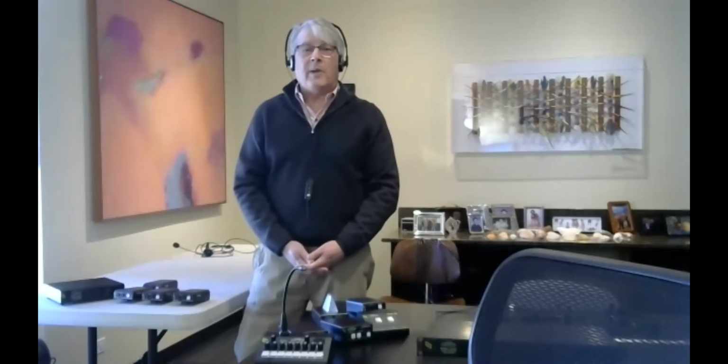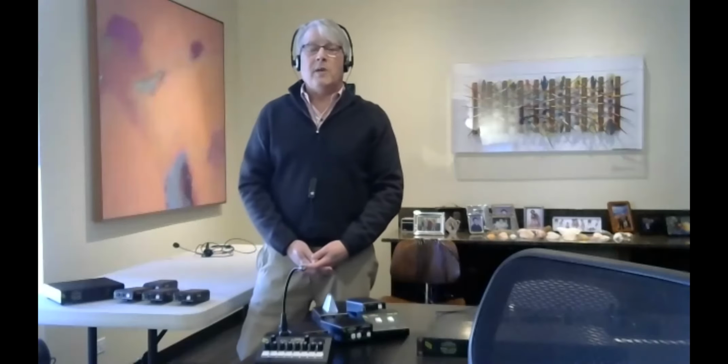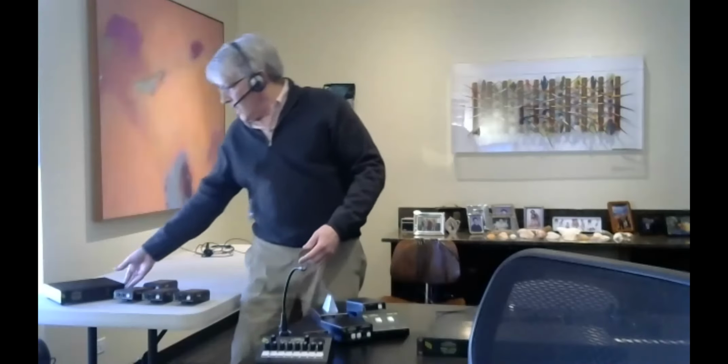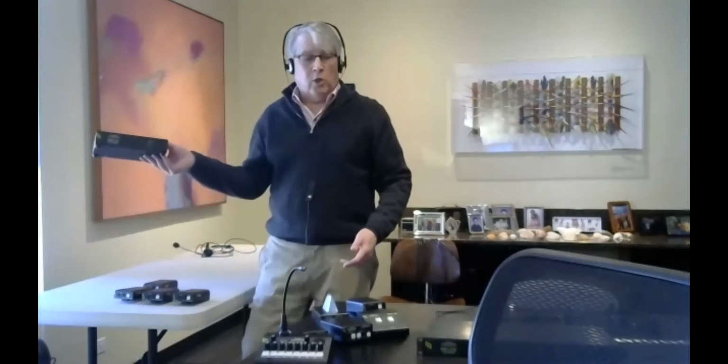That comes from telephone trunking when New York was connected to Schenectady by literally 4 wires, 2 pairs called 4-wire, a send and receive. So that's an independent audio path from me to you and a path back from you to me. So there's no way to directly create party lines, except we do it in the digital domain in this model 5421, which we'll hook up in a minute.